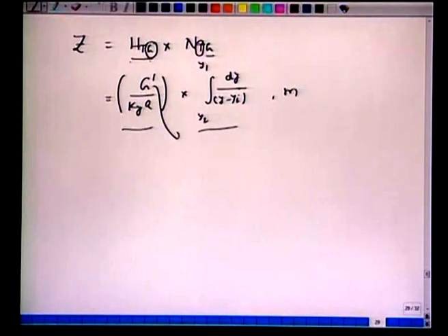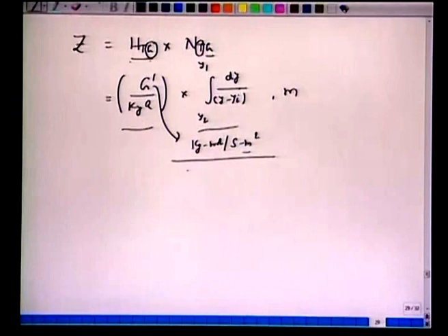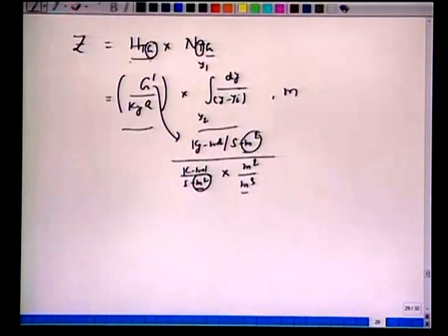So, this G prime is kilomole or kg per second per meter square cross sectional area, and we have this ky, which is also kilomole per second per meter square of interfacial area. So, this interfacial area is a meter square, but we have a, which is meter square per cubic meter of your packed bed column.